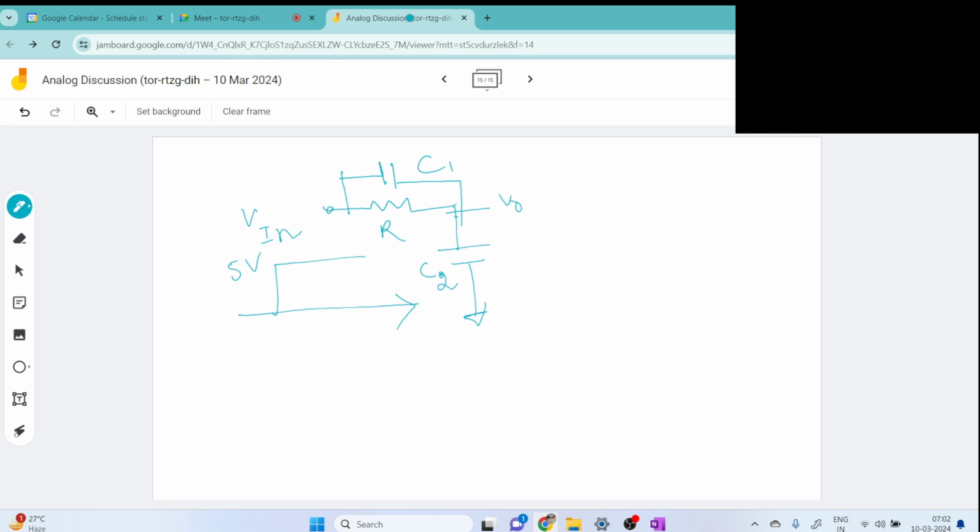We will be solving another question like this later. Let's solve the first one first. We have to comment on what the voltage will be, that is, draw the voltage versus time. We know that at t equals 0, the capacitor is a short circuit. If we do that, the circuit will look like this, and both of the capacitors are initially uncharged, with no initial charges. So this is 5 volt and this is our V out.